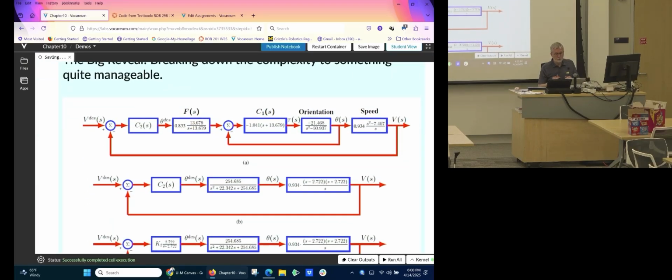So this is what we're doing now. Here's the PD controller for lean angle. There is the precompensator, theta desired to theta. Theta desired to theta is the second order system. So this transfer function is really this.